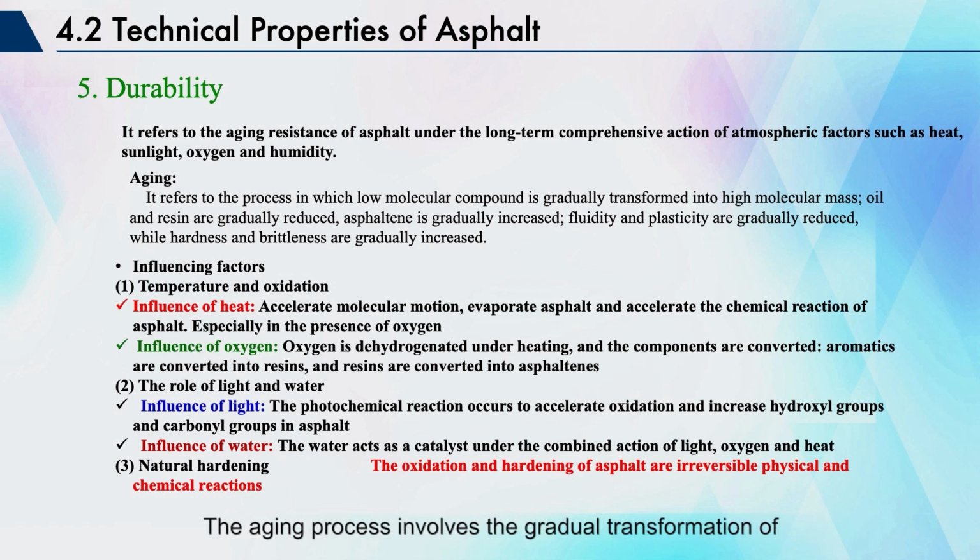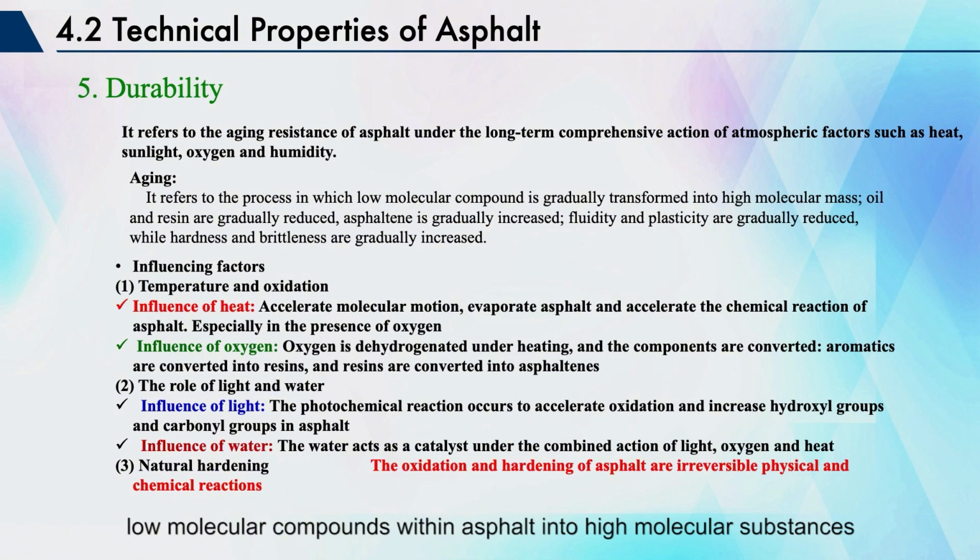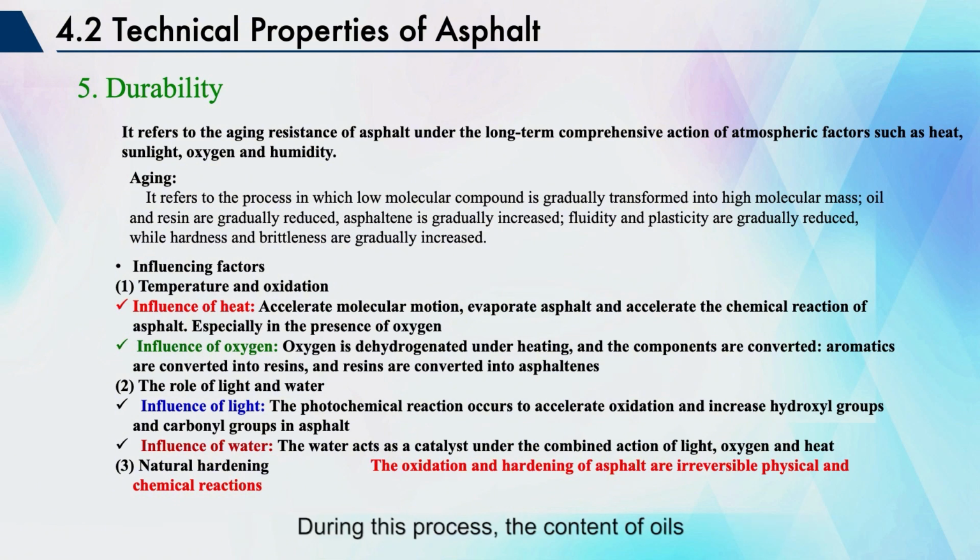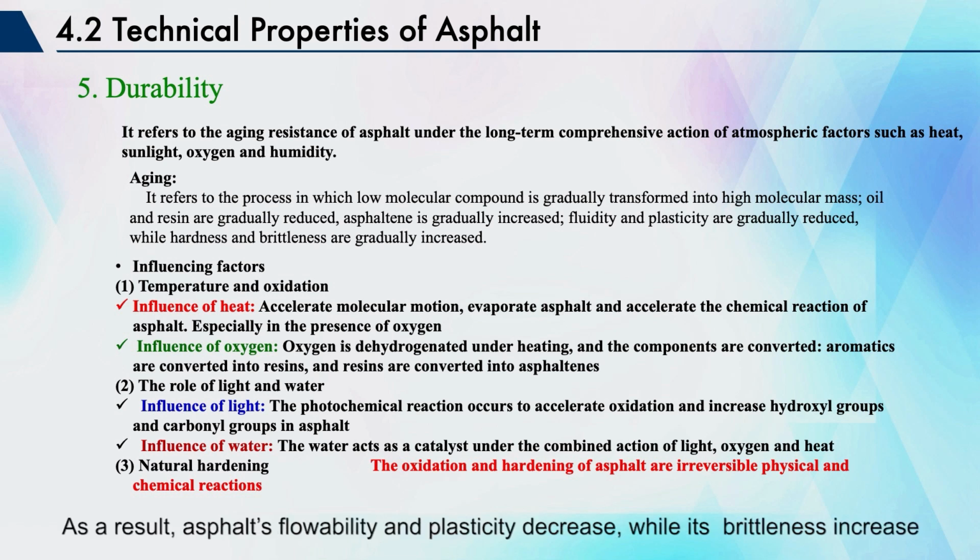The aging process involves the gradual transformation of low molecular compounds within asphalt into higher molecular substances. During this process, the content of oils and resin decreases, while asphaltene content increases. As a result, asphalt's flowability and plasticity decrease, while its brittleness increases.